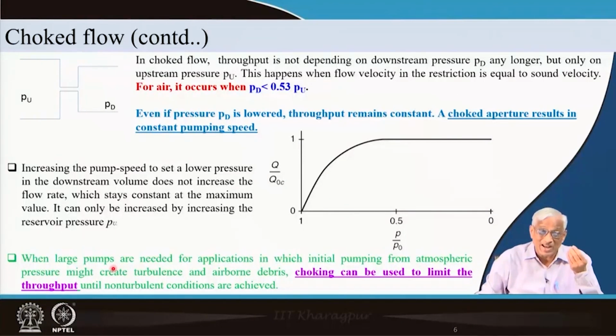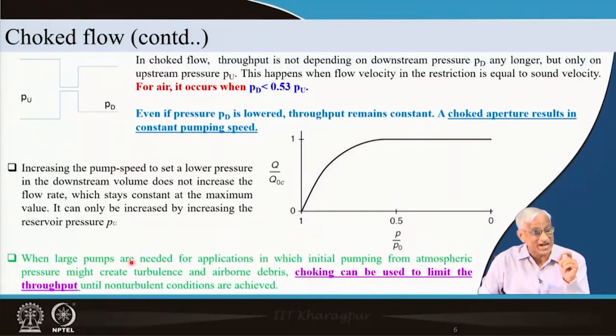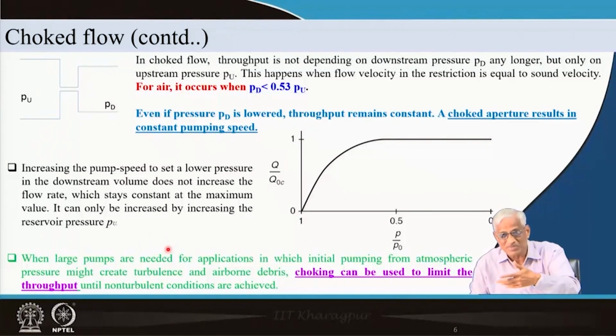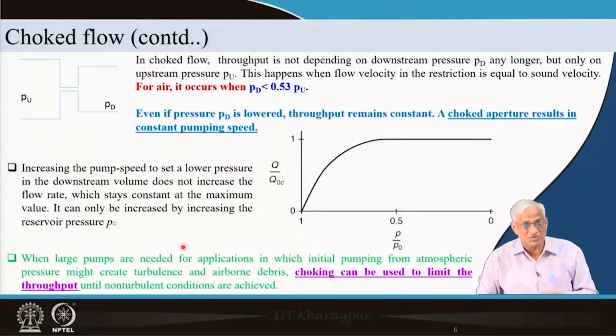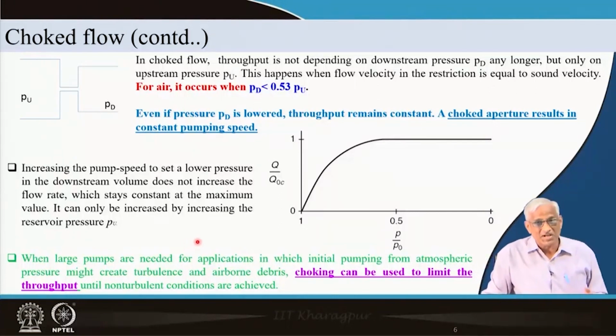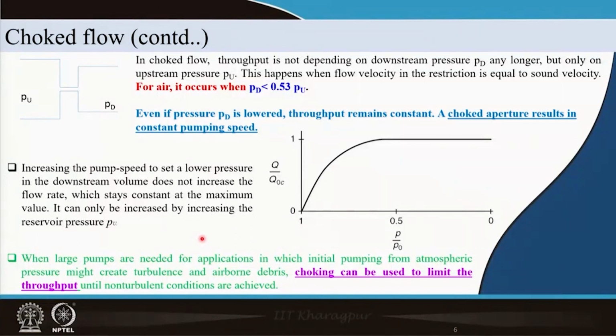There are some pumps which can handle particulates, like screw vacuum pumps. A certain amount of particulate it can handle, because there are gaps. These are dry pumps, there is no lubrication, and there is a gap between the parts. Roots blowers can handle it, but if you increase the particulates by a huge amount, they will fail. A water ring pump can handle the debris, but a rotary pump cannot, because it is physically touching and it will scratch, the pumping action will cease and the oil gets spoiled. Then you have to open the whole thing again.